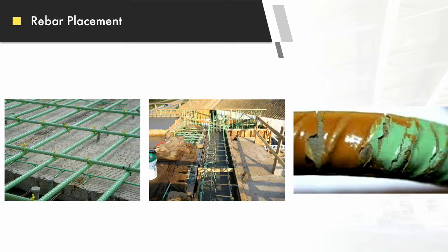So the things I'm showing you are just stuff that I see happen quite a bit that we really need to be paying attention to, because of the longevity of that abutment with the rebar right there. This one doesn't have a joint over the top of it. This one is just tied approach slab to deck with the joint out on the outside of the approach. But nevertheless, at that point, you're still going to have a cold joint. Water can get through there, and it's going to affect your abutment, eventually your bearings, and it's not going to give us the life that we need in our structure.